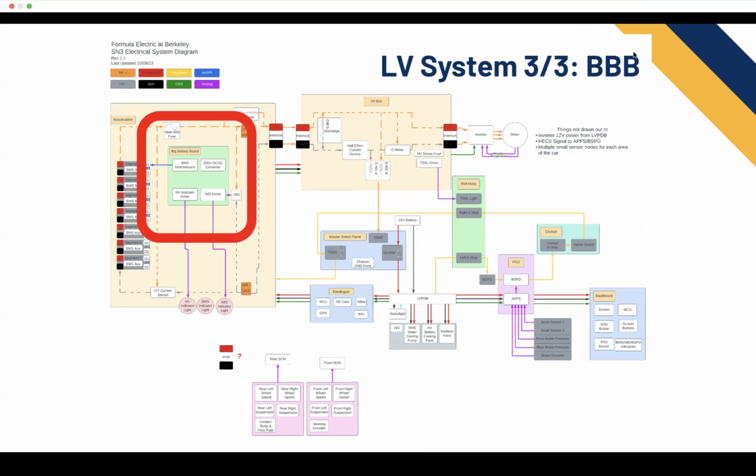That tells you if there's high voltage beyond the AIRs. The reason that has to work even on a table is, say the accumulator for some reason thinks, I should close the AIRs and send high voltage out. Obviously that should never happen on the table, but you wouldn't know if high voltage was exposed. That's why you need this light to indicate it.